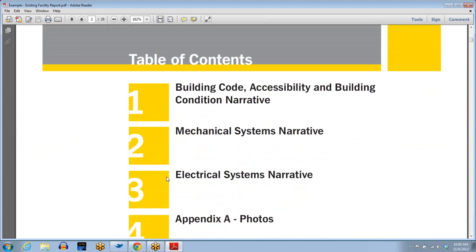You look here at the table of contents, building codes. You have to obey them. If a code is adopted after you have built your building, you're grandfathered in. But once the building code is done and you go to bring your facility up and repair it, depending on how much work you do and what work you do, the building codes may require you to bring your whole building up to the current code. Any new buildings you have.